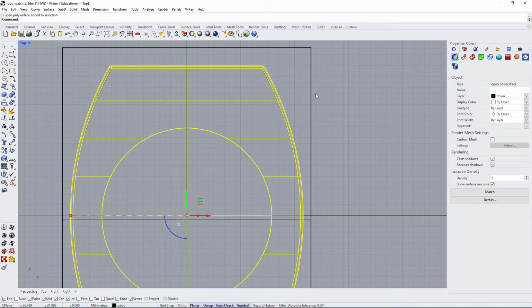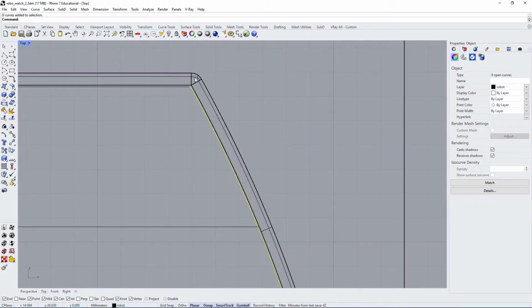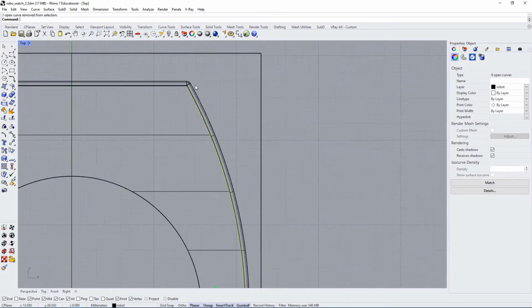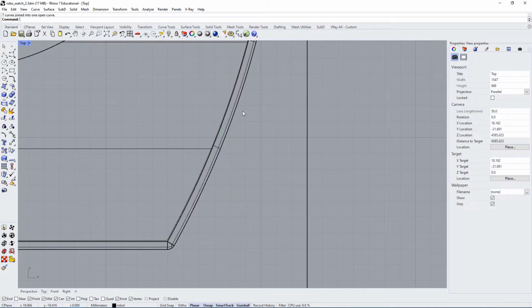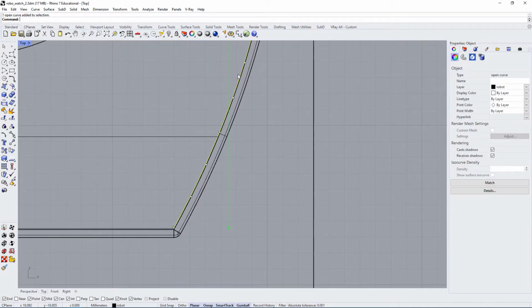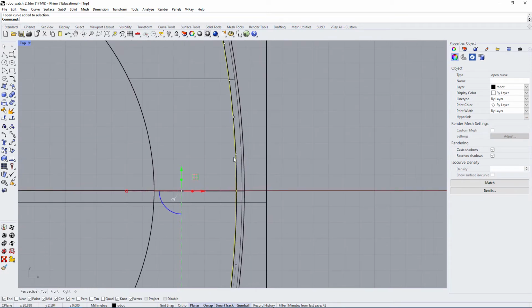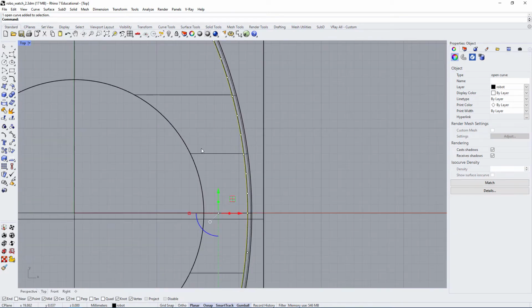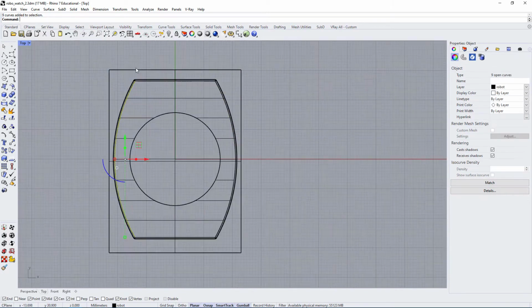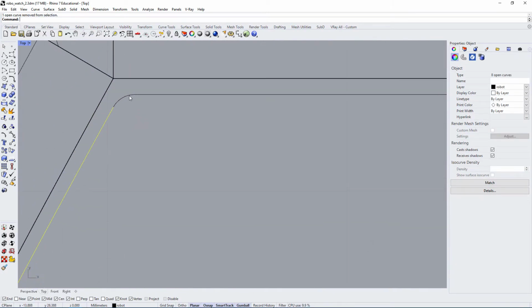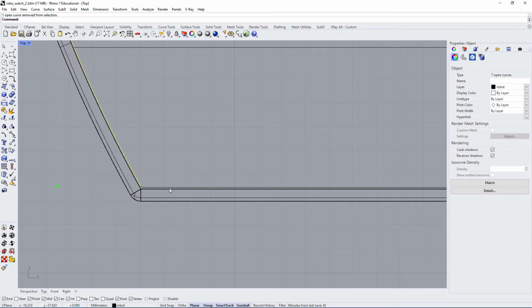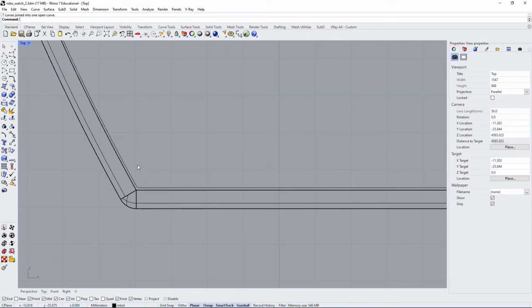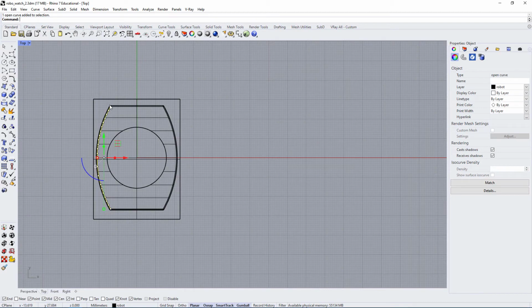So sometimes you get this where one of your curves is overly complicated, like it doesn't need to be so many edges. So we'll join it, but what you'll see here is it's broken up into small segments, and we don't need that. We can have it be a single curve. Typically to fix that, you can just join everything. Just be very careful about the corner one. We don't want to join that. Yeah, if we just remove the two corners and then join them so that they're a single curve. I don't want these long curves here to be broken up into small segments.